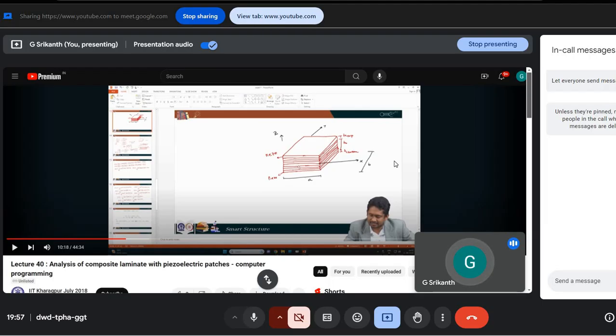When you compress a gas like air, it gets hot. If I take a compressed gas and then let it expand, it gets colder. So when gases expand, they cool down, end of story. But maybe not. We got room temperature 73.9. Open the valve, and it quickly increases to 75.4. It's actually warming as it's coming out, not cooling.